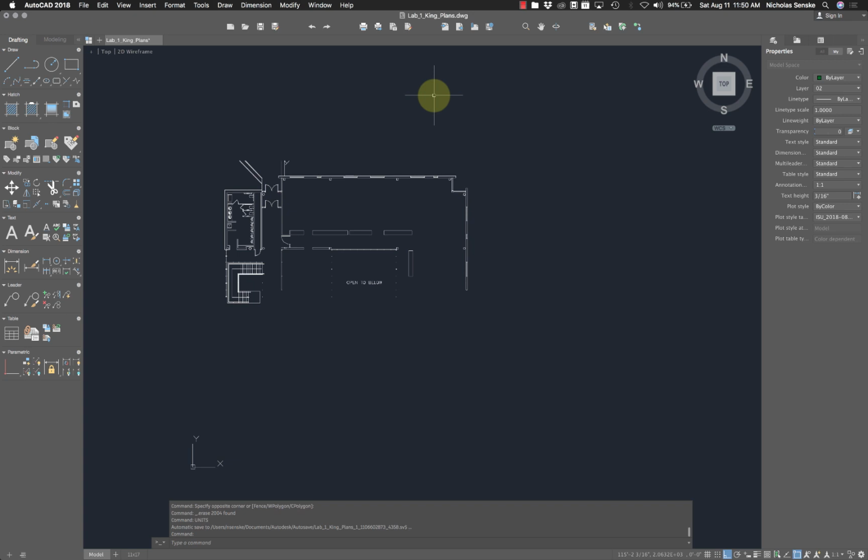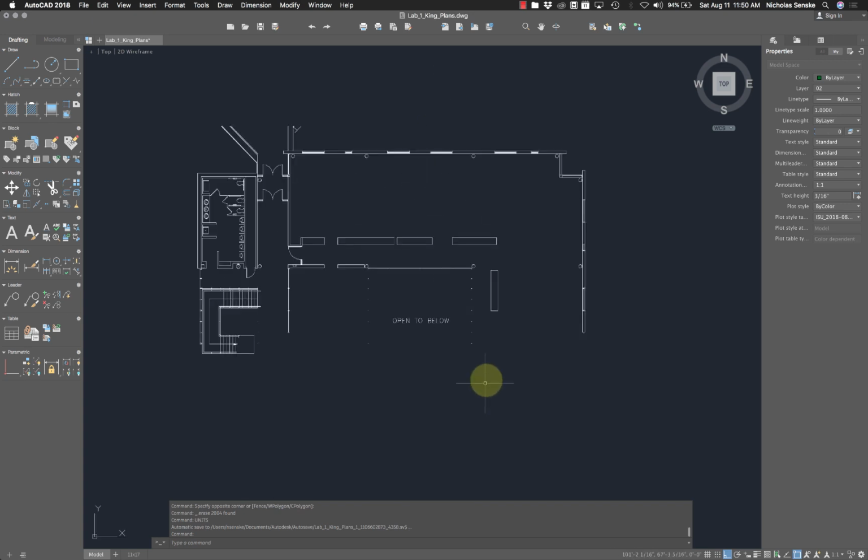You make the drawing in CAD at the actual dimensions, no matter what, okay? Whether it's a mile long or it's only an inch long, you draw it at that scale, and you use those units. Don't do any unit conversion in the drawing. That's what the layouts are for. When we go to make a drawing actually to print, you will determine what that scale is, okay? So that's really important. This drawing is like 100 foot is 100 foot.